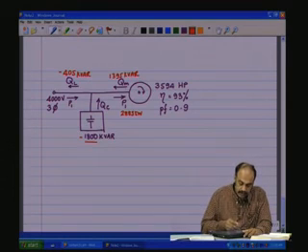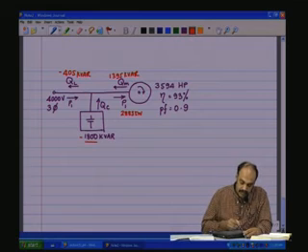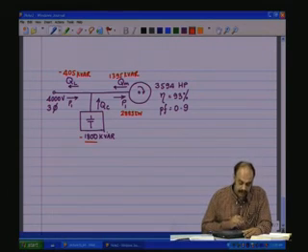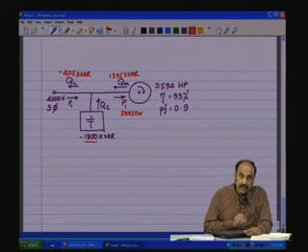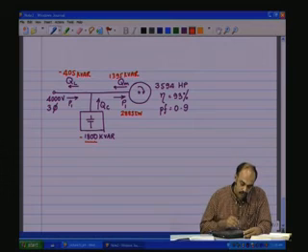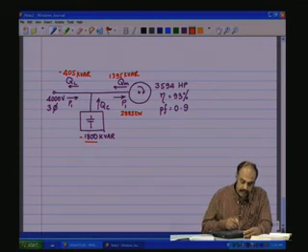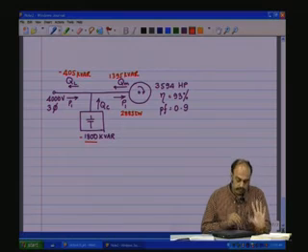The reactive component of the load alone would have been 1395, but because we have put this capacitance compensating network, the line side kVAR has grossly reduced, and in fact it has gone leading. It has gone into the capacitive side as minus 405 kVAR. If we had put only 1395 kVAR rating capacitance here, that would perfectly cancel, and the reactive component on the line side would be 0, and the line would be just giving you active power.